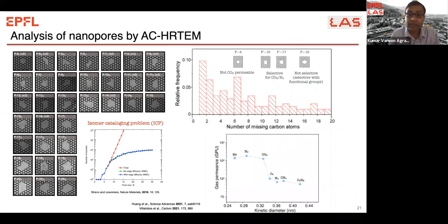And indeed it is. When we plugged this into the gas permeation module, we immediately saw a much higher transport rate for helium, hydrogen, and CO2 compared to the transport rate of nitrogen, methane, and propane. By the way, this is a log axis plotted as a function of the kinetic diameter, right? Hydrogen is faster than helium because hydrogen adsorbs slightly more than helium, which essentially doesn't adsorb on the lattice. Then CO2 tends to decrease because CO2 has a larger size than hydrogen, but still adsorbs much more strongly than hydrogen. So there is a clear cutoff between CO2 and oxygen and nitrogen.